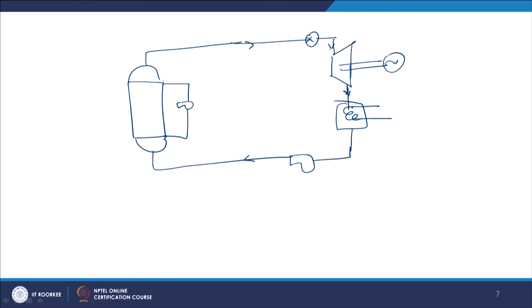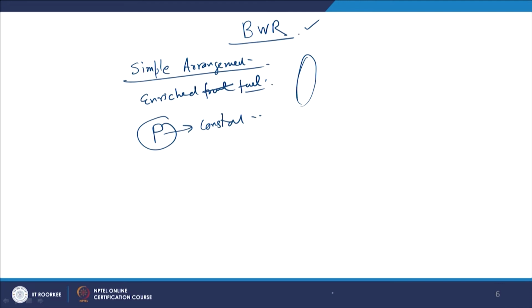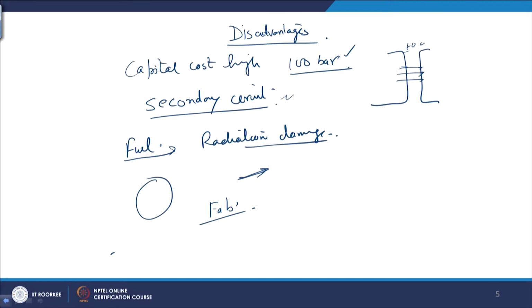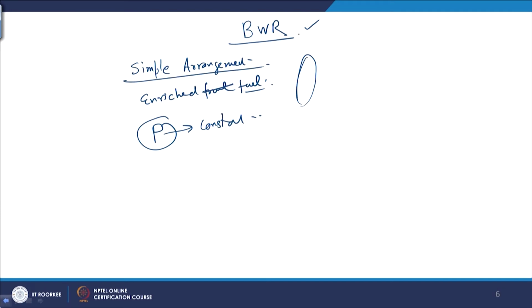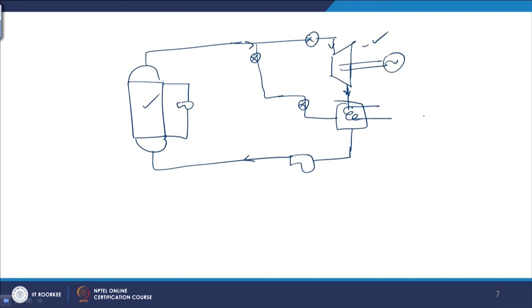Now, there is a certain decrease in requirement of the power. We need less power. But the reactor core continues to generate the same amount of steam, and steam is bypassed. Steam is bypassed and it goes to the condenser directly, bypassing the turbine. Right? In that case, the efficiency is reduced drastically. So, if you look at the advantages of boiling water reactor.